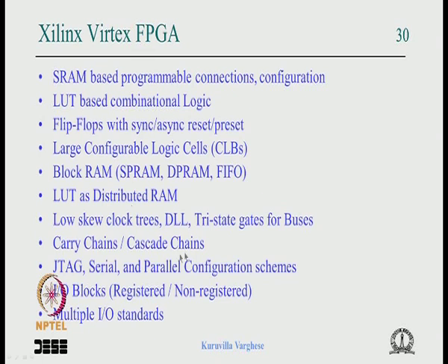So this is a summary. Basically it is an SRAM based programmable connection and configuration. The lookup table is used as combinational logic. You have flip flops within the logic block with synchronous and asynchronous set or reset. Large configurable logic block, it is quite big.